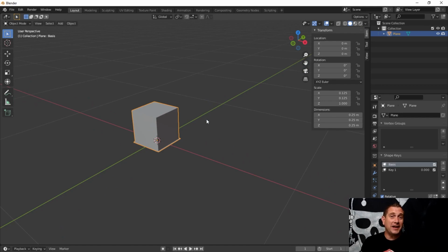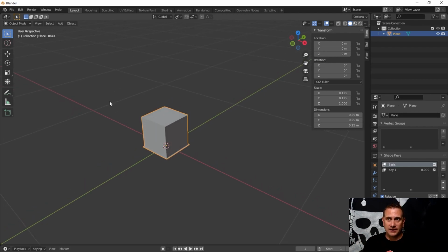And we essentially now are at the place where we have a plane that's been very, very rudimentarily modeled into a bar. And then we've extended the positions of the top face with a shape key, and it has 3 UV maps attached to it. That's pretty bonkers so far, right? Okay, so now we're in a place where we can start to build out a mesh where we've got a grid of these bars that's 16 long by 4 wide, okay? And we can do that by starting to duplicate this mesh.